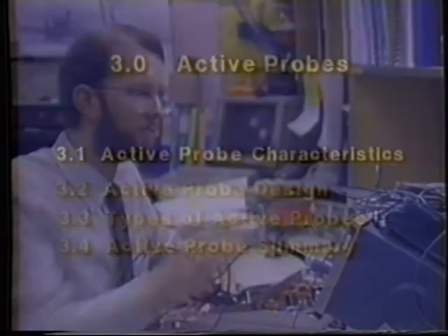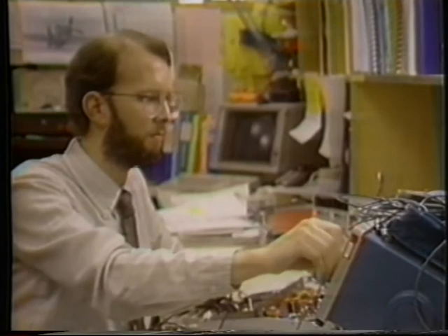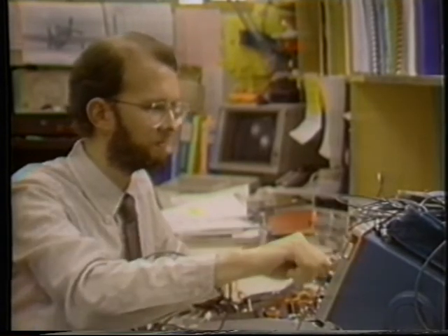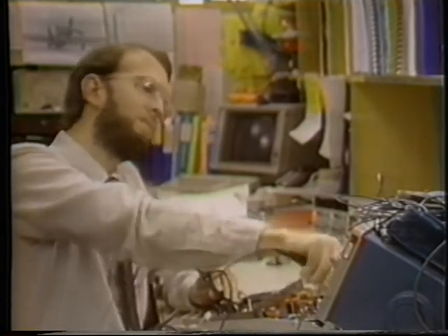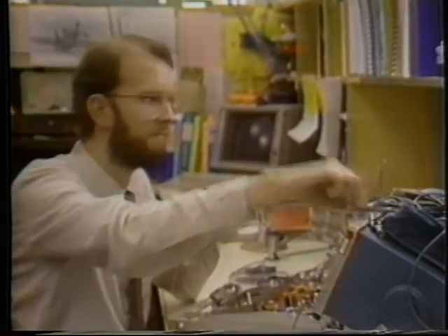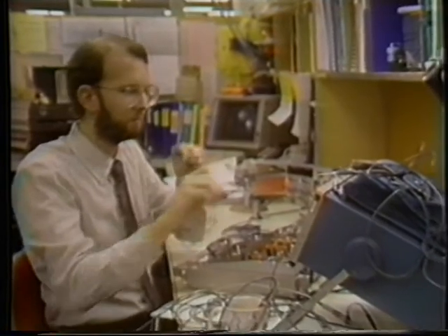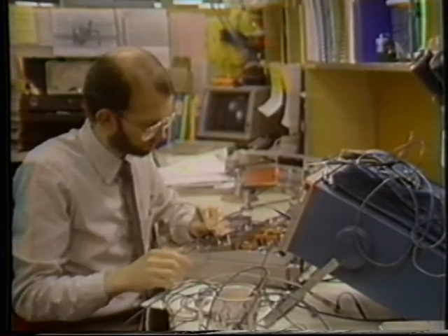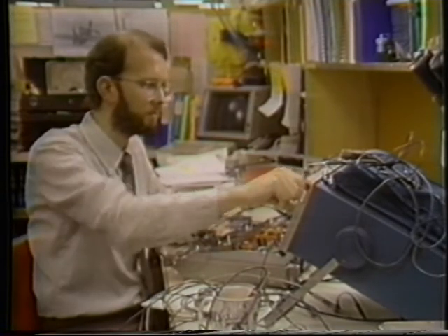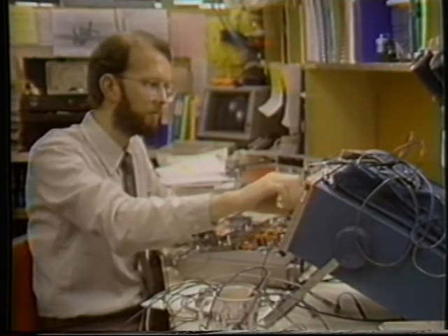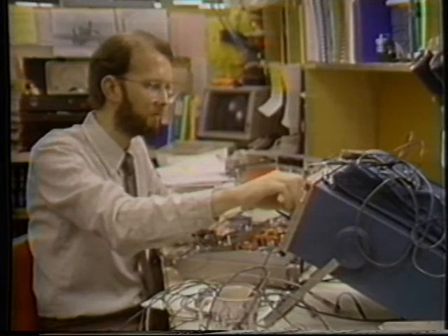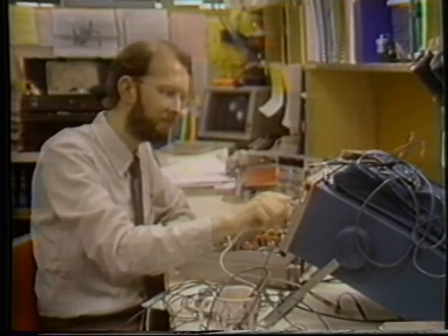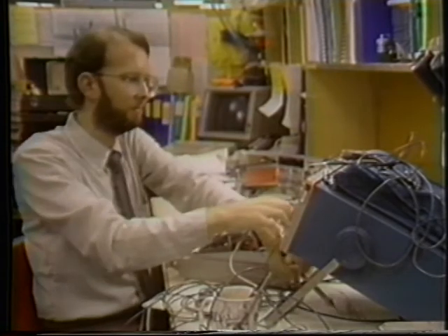If high Z and low Z probes are effective in so many applications, why do we need any other kind of probes? Your answer is that you may not, but let's suppose you have a problem that's a little different. What if you needed to make a measurement on a high impedance, low amplitude, high frequency circuit? A low Z passive probe might be a good choice. It has the low input C that we need, but the comparatively low resistance it offers will pull the circuit point to near ground, unbias the circuit, and destroy its gain.